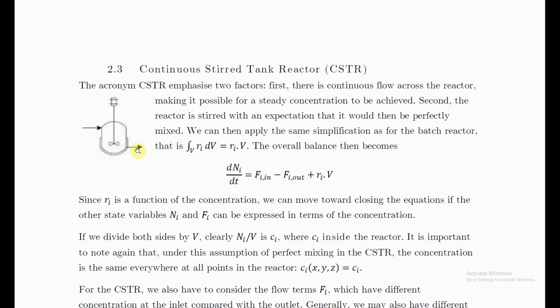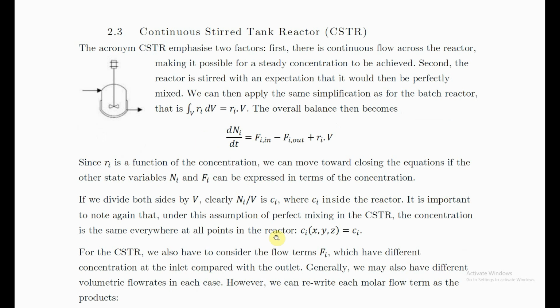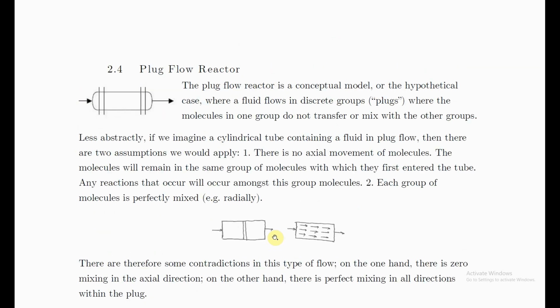So to get the same productivity that you get from the batch case and from the PFR case, you need a giant CSTR. So the CSTR is a very bad user of its reaction volume. The better your conversion, the worse your reaction rate, and the greater the volume must be for you to achieve the same production rate. So those are topics we will come back to later on, but that's important to think about right now while we're talking so fundamentally.